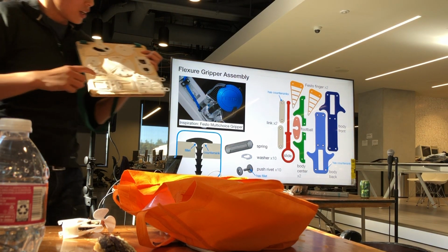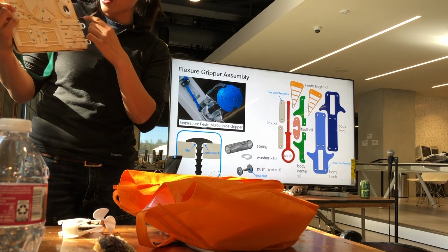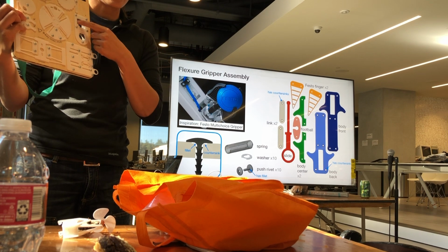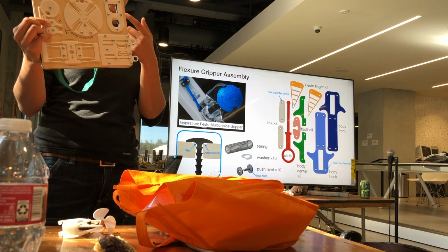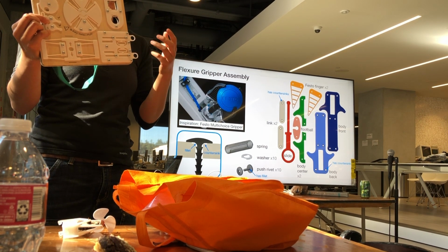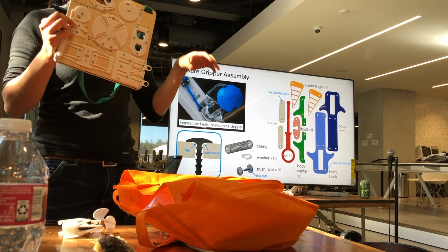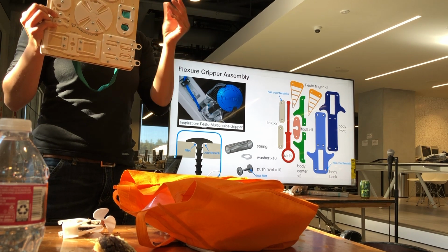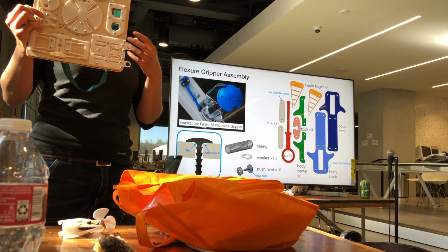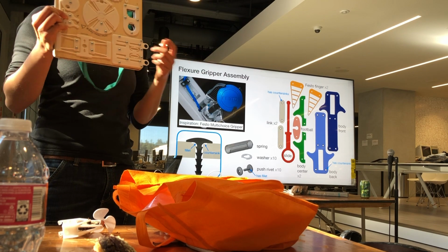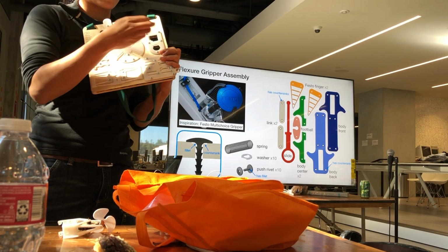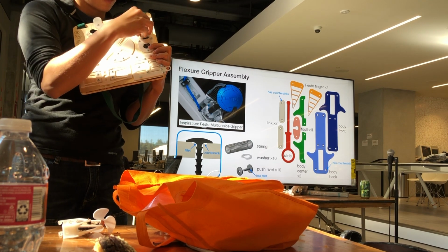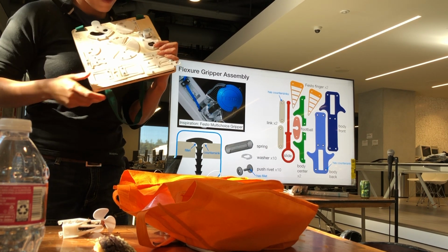This one here, it's hard to see, but when you get it up close, you can take a look at it. There are 2 holes, but there's a compliant structure in each one. This is to show that it's a good way to hold, let's say, a bunch of motors or parts or sensors that you want to hold, where there's some variation across all of them. You can just design an interference fit, and that interference fit is probably enough to take up the variation in your part tolerance. So that's an example of that.